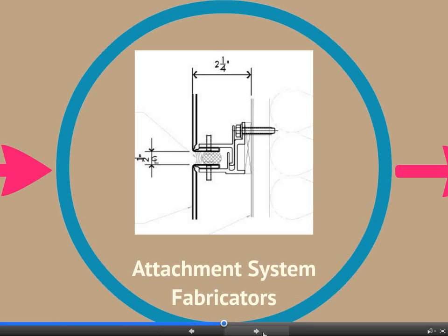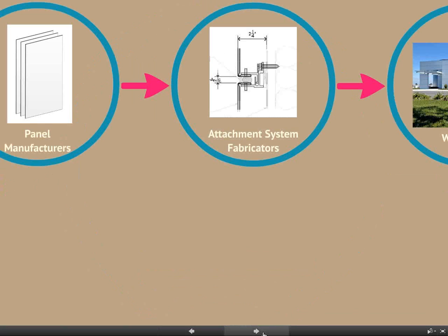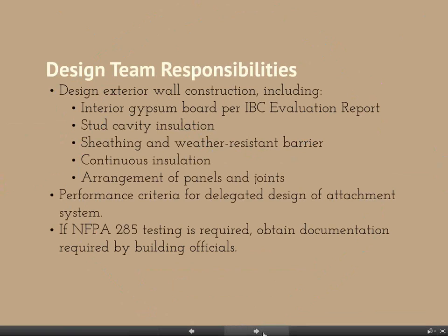So they're using that to provide the continuous insulation plus the weather and air barrier all in one product. All in one product. And that probably would simplify a lot of the issues relating to the NFPA 285 testing, because those guys, Sentry and Kingspan to name two, have done a lot of testing for that in particular. Yeah, and I would suggest that kind of a system would work well when you have a lot of opaque wall, because the panels you're trying to deal with are limited by dimension.